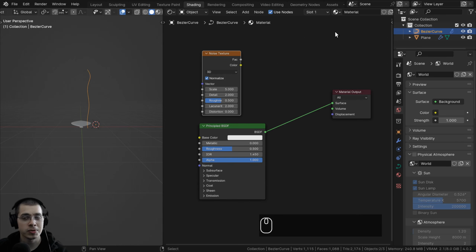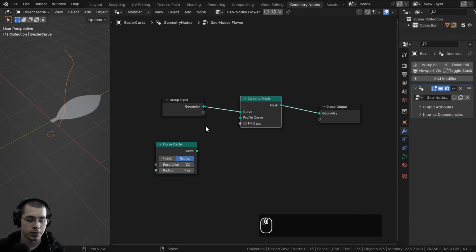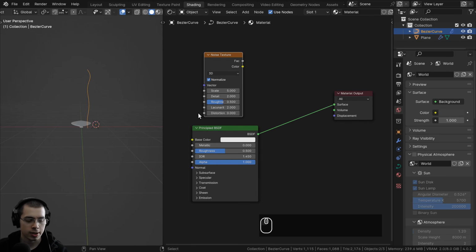Now, just so that you're not confused, the shader editor also has nodes, but it's editing the actual material, not the geometry. If you are in the shader editor, you press the Control and Shift key instead. So you hold down the Control and Shift key and then select different nodes to preview them. That is different from the geometry node editor. So in the geometry node editor, it is the Shift Alt key. I just want to make sure you weren't confused by that, because when I was first learning geometry nodes, I was kind of confused. So in the geometry nodes, it's Shift Alt Select to preview the nodes, but in the shader editor, it's Shift Control Select to preview the different nodes.